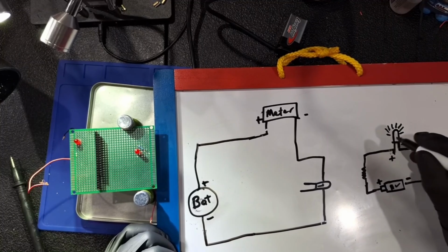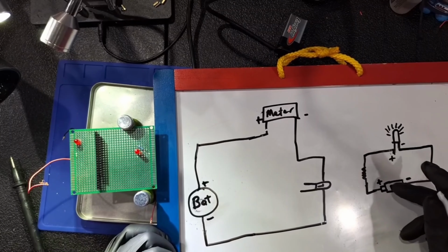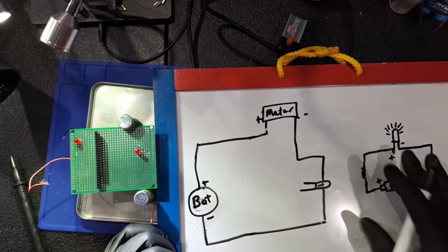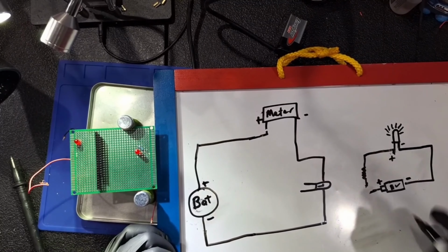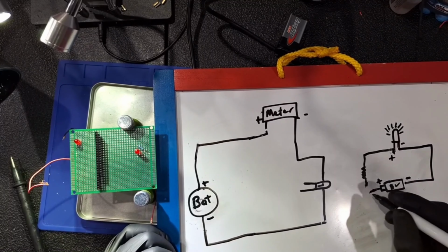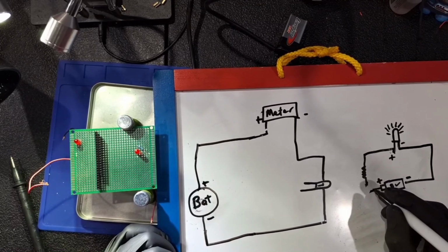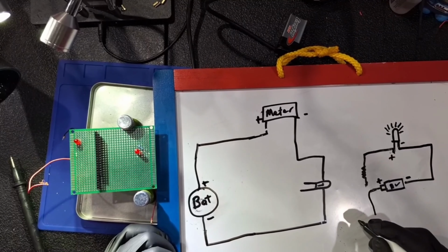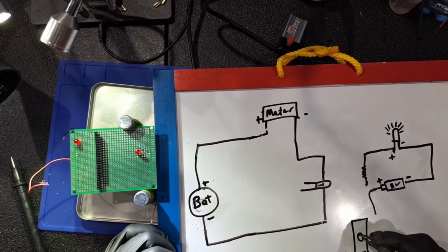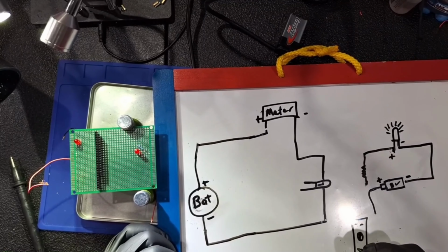So currently this is the basic circuit. And to break the circuit, I already know that I have to break it from the source, from the positive side connecting to the battery. So I'm going to simply break right here at the battery, and I'm going to connect the red probe from the multimeter onto the source. So let me just quickly draw a multimeter here.